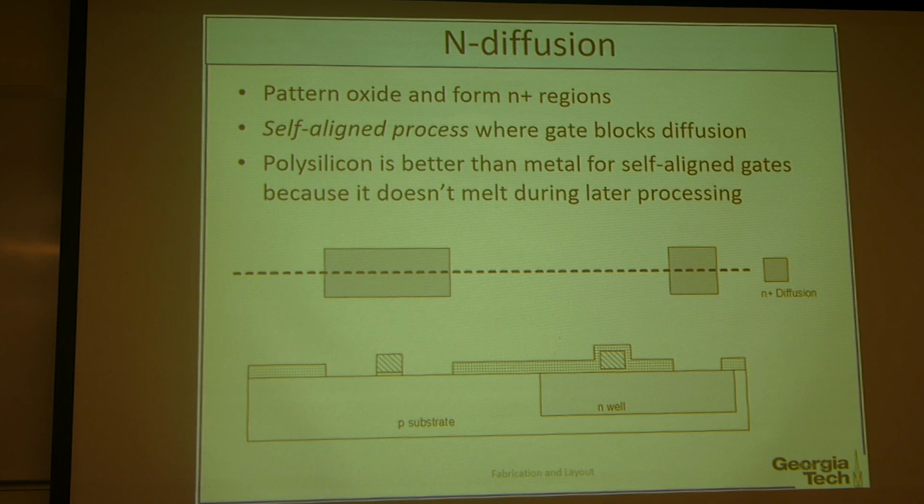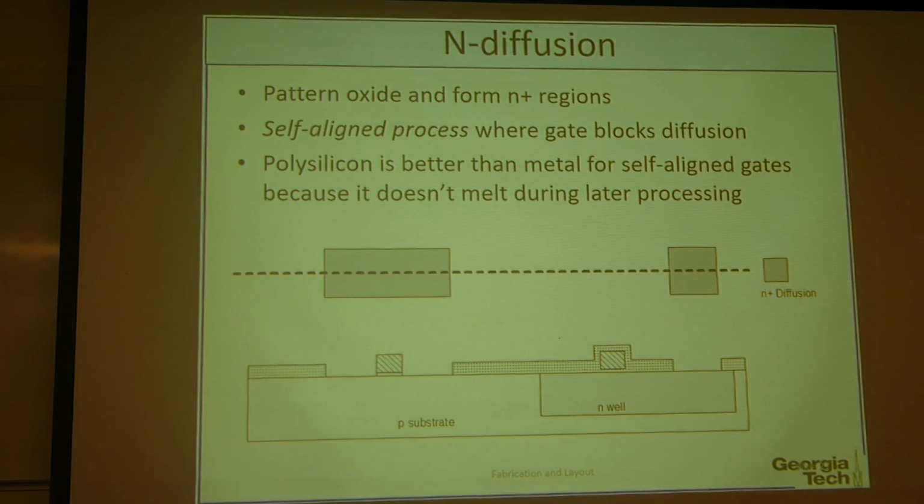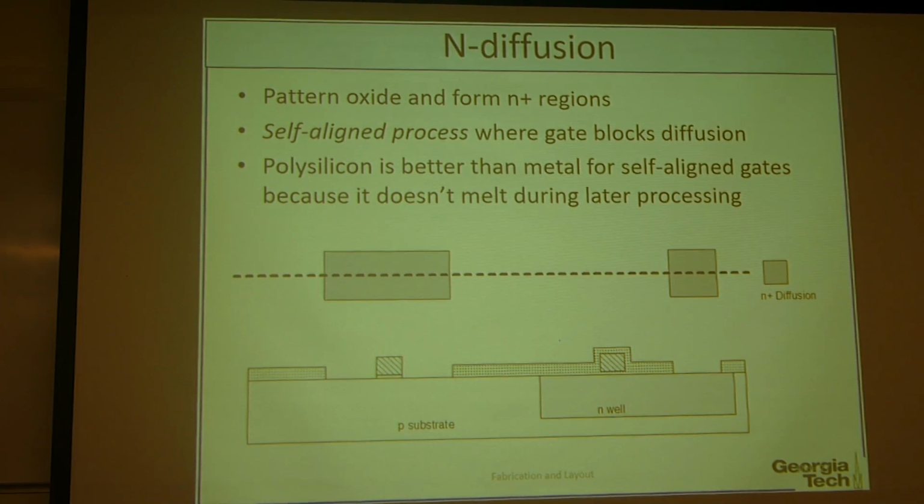And you can notice that the source and drains should be located next to the gate here and there. But if you look at the mask here, the gate side is also open. This is because the gate can block the ions coming from the implantation tool, and it can work as a mask itself. So it's called a self-aligned process, because it can self-align without a mask.